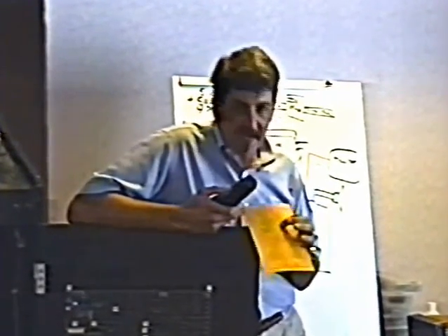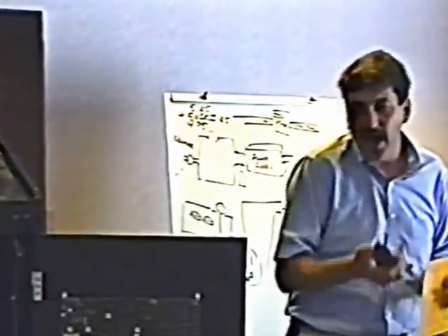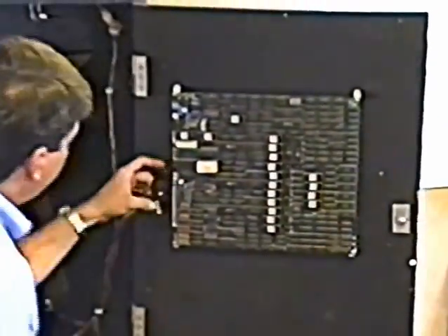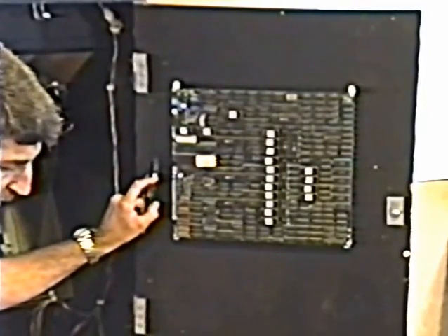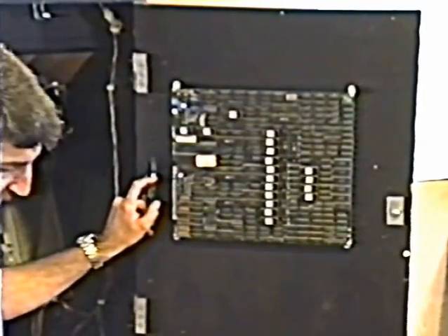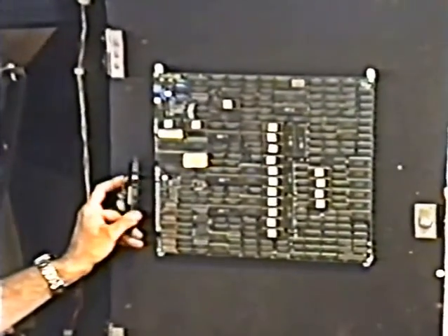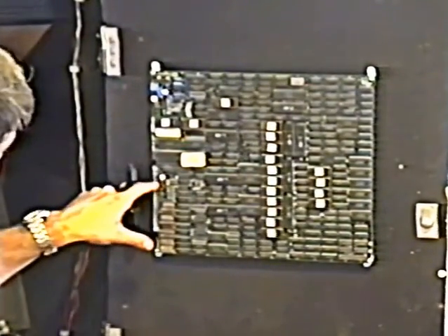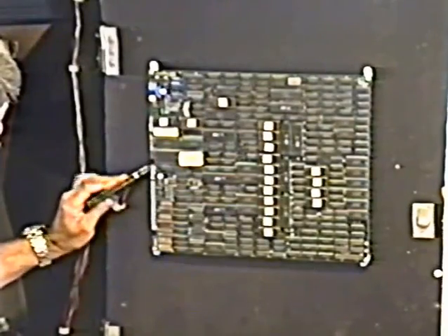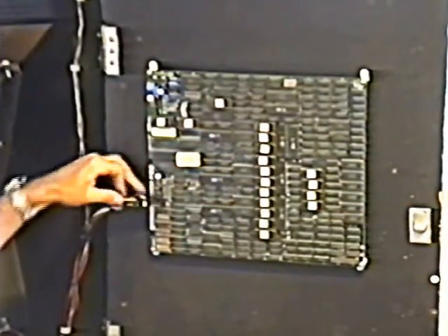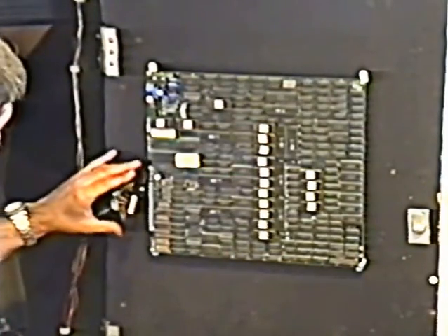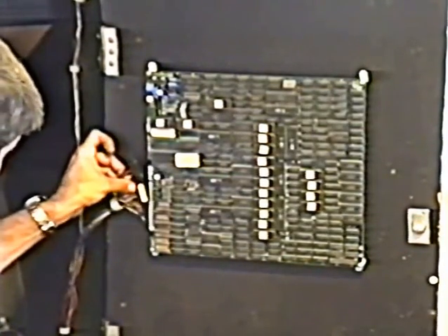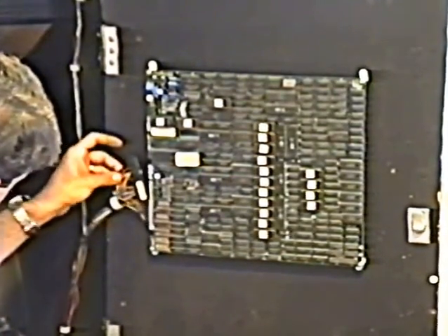And then pin 7 and H is what we call the keyway, and that's a blank spot on the connector. If you look at the connector, you see this little white part right here. This is a keyway, and there's a slot in the board right here. Essentially, it keeps you from plugging this thing in upside down. It idiot-proofs the connector so that you don't run power into the wrong part of the connector. You may find that the minus 5 volts is unused in some games.